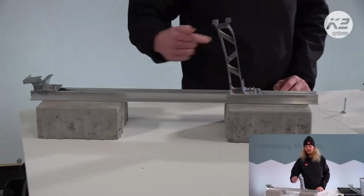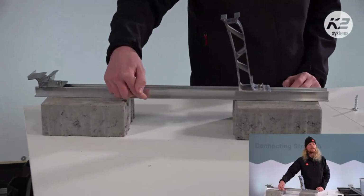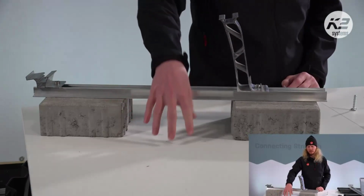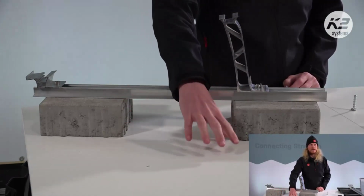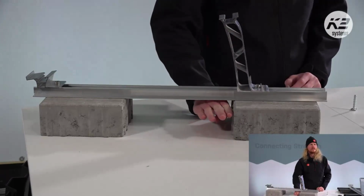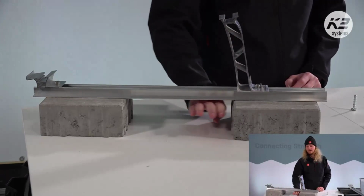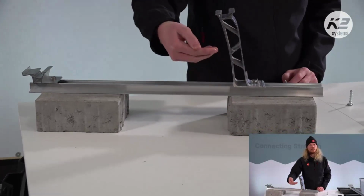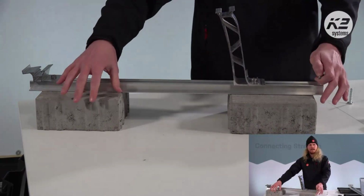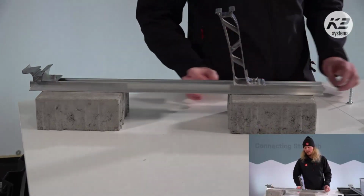And just to maybe have a visual note of that as well. This is the height we're talking about here. So in this case, right now, what you see, imagine there's no ballast at all. It's just sitting on the roof. Generally, the ballast will be 5 to 10 centimeters, which will sit sort of up here. You don't have that much height between here and the module, but you can raise it up further if you need to, if you had higher, thicker ballast blocks.